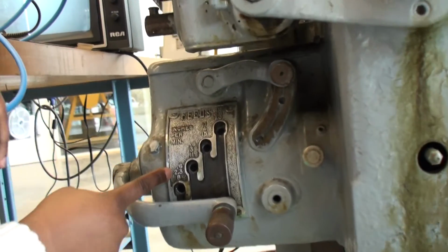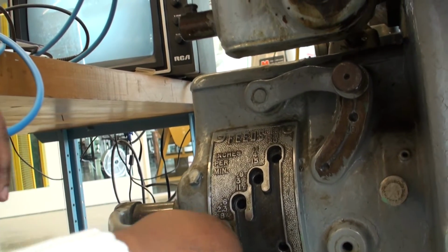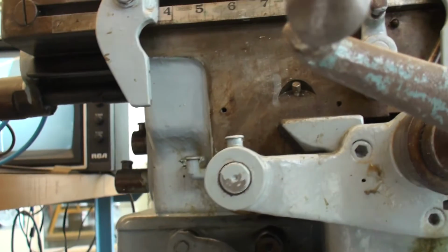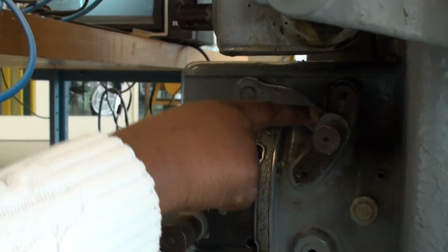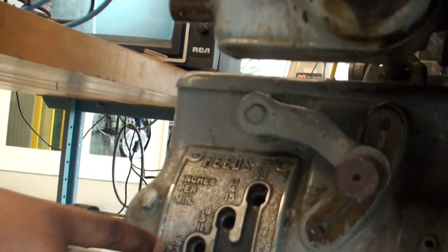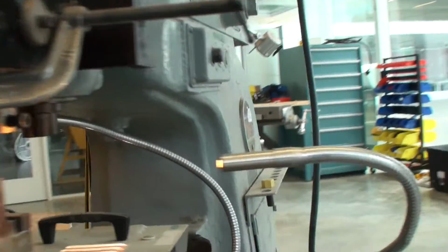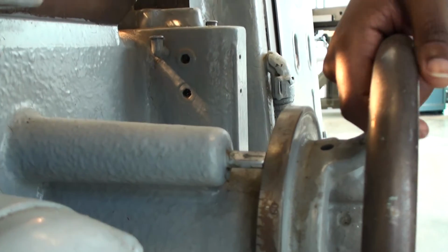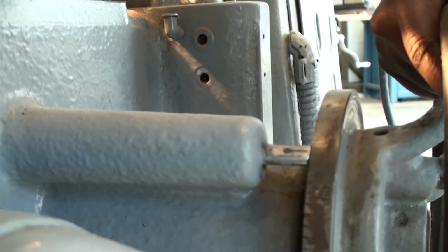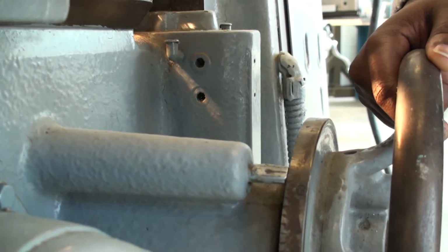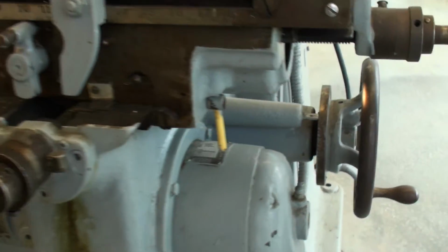2.3 is the second number down here, so we want to bring it over on this side, and then you put this on medium. So the slow up here, medium, and fast. So we want to put it on medium because it's the second speed right here. And then we go and adjust our depth of cut again. So once again, we're just moving it down 4 tick marks. So 1, 2, 3, 4. Yeah, and we're all set to go.